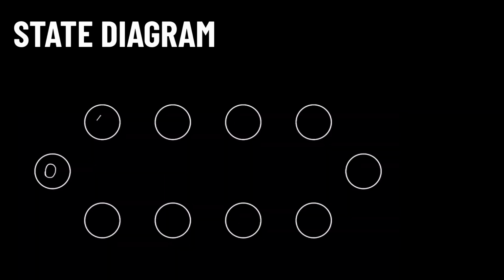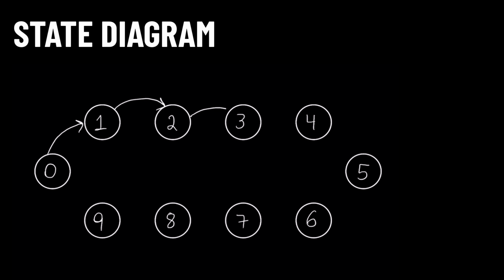A decade counter is a counter that counts from 0 to 9, either up or down. The state diagram depicts this. You'll build a synchronous decade counter in lab, so I won't spoil the fun about what the expressions are. The same process goes into building a decade counter, but now there are 4 flip-flops required to build this. What happens in the transition table when the current state is 10 or higher? Treat those as don't care situations.